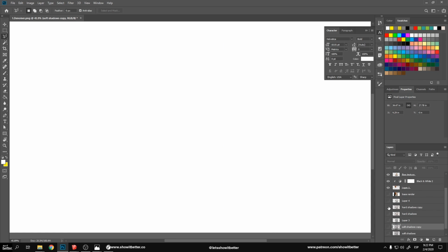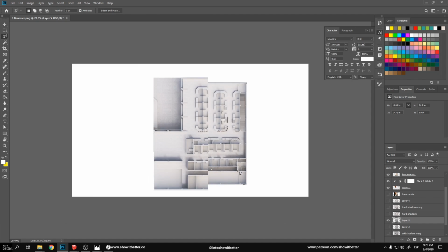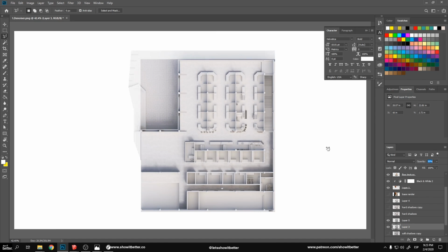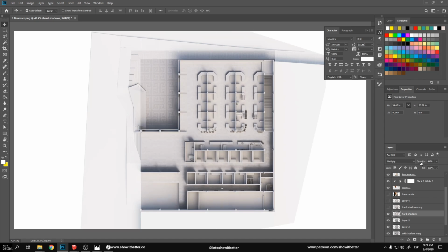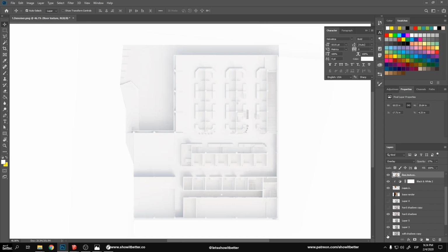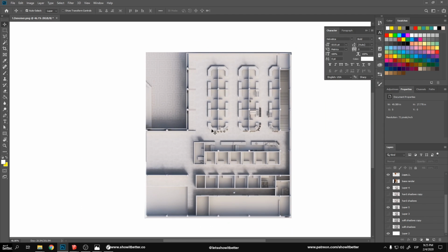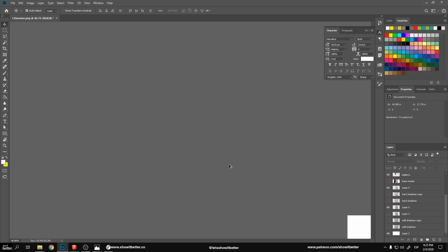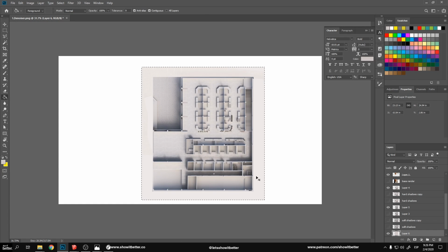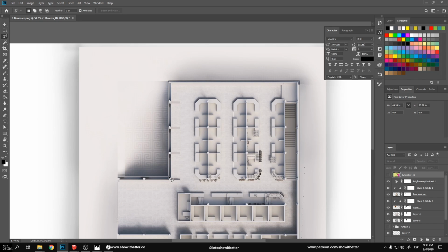So what I did, and I'm just gonna speed through this because it's not that important. It really depends on the building, but in this building I had sort of a problem making it look well. So what I did was just erase the whole context, and I made a lasso selection of my building, and put it in another layer. Control J, put it in another layer, and I applied some soft shadows outside of the building, so it still looks like it's part of a normal render.